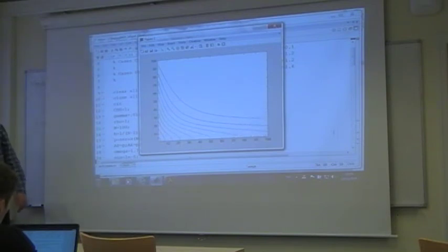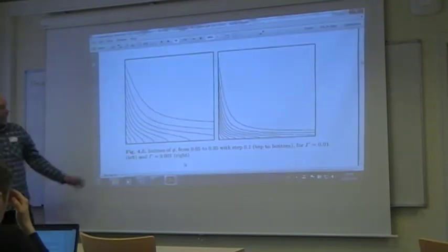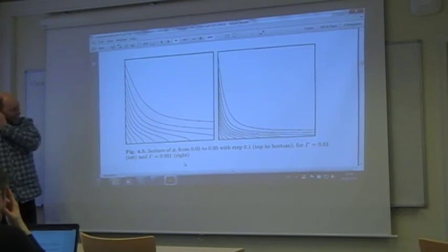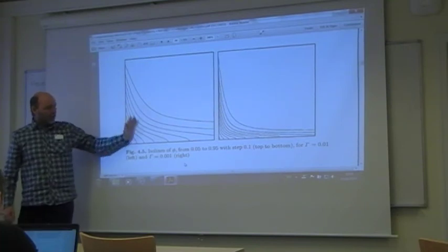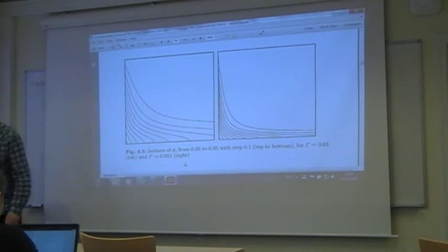This is the upwind, the central scheme. The other one was the upwind. But again, you can't really tell the difference between those two. They will be very, very similar indeed. Although the first order upwind, as we know, has more diffusion with it, has more viscosity, so it will push more into it.